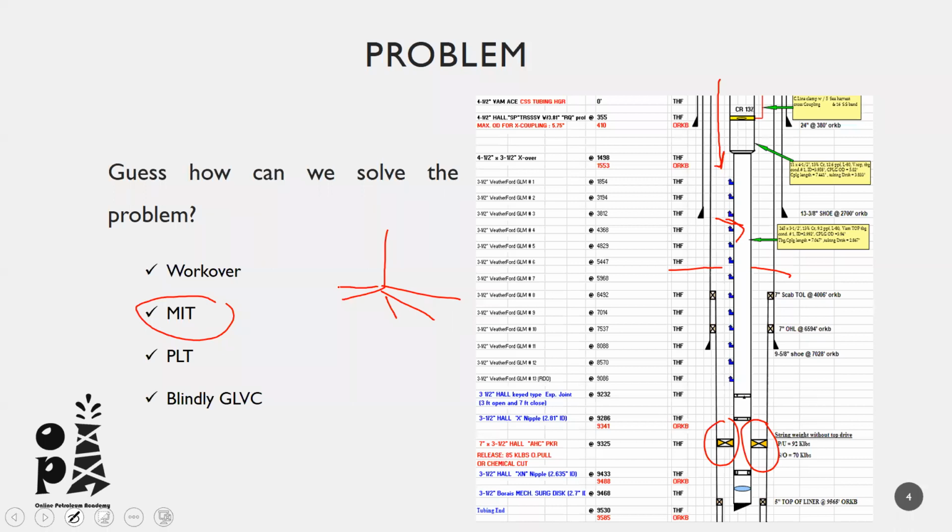So when you run with this tool, you can easily identify the positions of the holes in your completion. Sometimes it may help you to identify the condition of your completion and whether it can be solved or not. Sometimes the corrosion of your completion is severe and you must also go with workover to solve the communication problem. And in other situations, there are only one or two holes that can be solved by a straddle system. For example, there are certain through tubing straddle systems that can isolate any possible hole inside your completion depending on the condition of the corrosion.